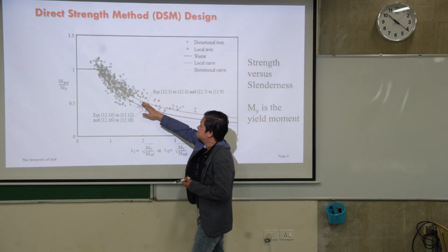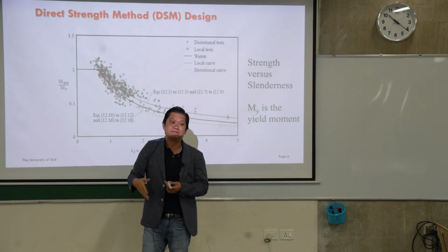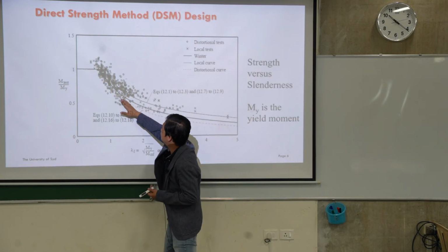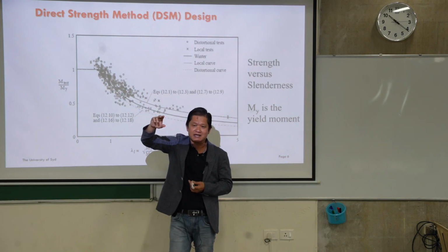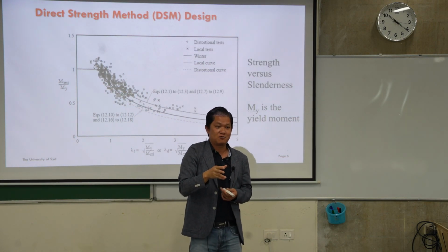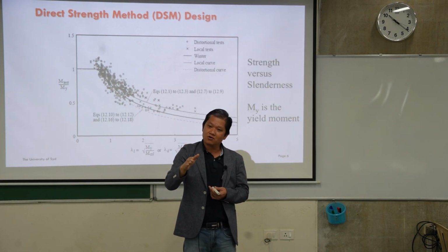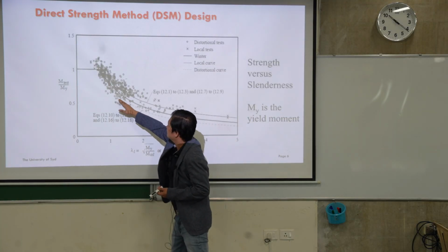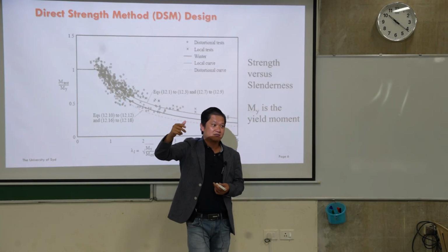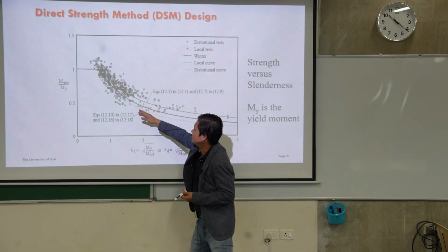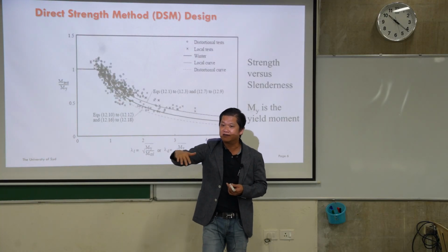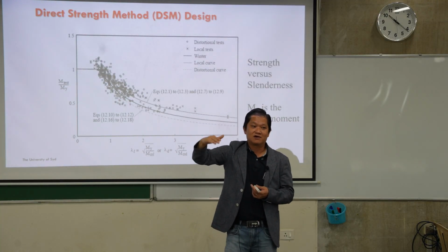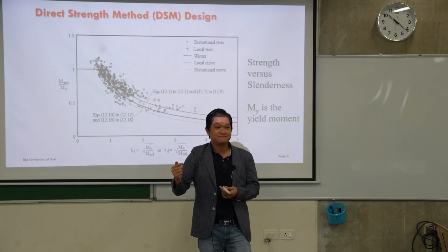First, you take the mean, as in the US system, or you take a lower bound, as in the European equation where they calibrate. So in European, it tends to be a little bit down here because of being conservative. But when you put it down here, it means that you have a more conservative equation, then you get a less phi factor.